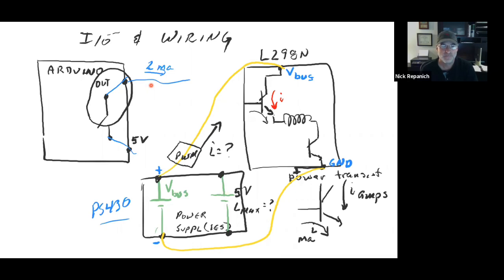Back to repair. There are special connectors. The ones I love using are made by Wago, and they have a little flip latch. You put two wires in there, flip the latch down, and it cinches them together. They're very handy and the wires don't come out. Especially when you're hooking up motor wiring. If you have an inductive load and a wire comes out, that's a really good way to have an energy storage device immediately spike the voltage on a transistor and blow it.